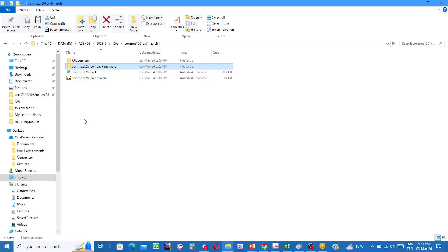So if I see that the stress value at a certain point is equal to or greater than the yield limit, that is one case. If it is less than the yield limit, then the basic stress analysis tool of Inventor can be used. But if the stress value, at least at a point, is greater than the yield limit, then we need to use either Fusion or Inventor Nastran to deal with such a design problem. This classwork says the material is to be in the elastic region. Yielding is not allowed.